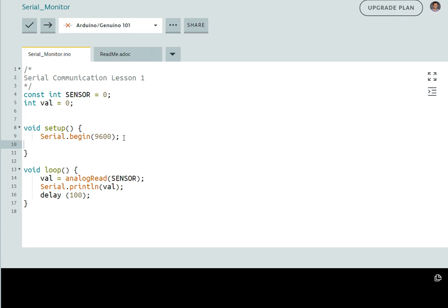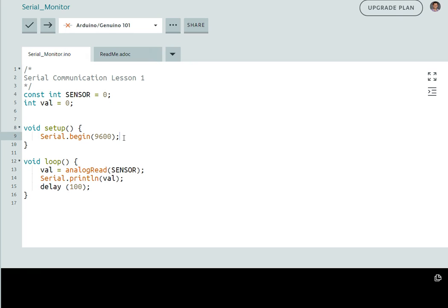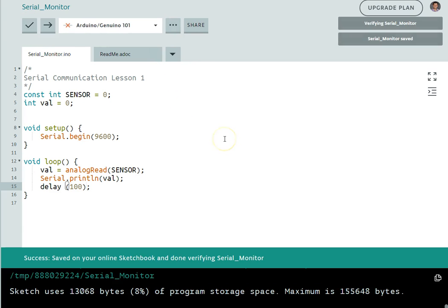Serial commands require the S in serial to be capitalized, and then everything else is lowercase. Something to keep in mind, semicolons. Your delay command, that can always be an issue. Really, stuff like this, you're just making sure you have semicolons. We could verify this right now. Hooray! So we know that this is indeed working, or would be working when we get it hooked up.